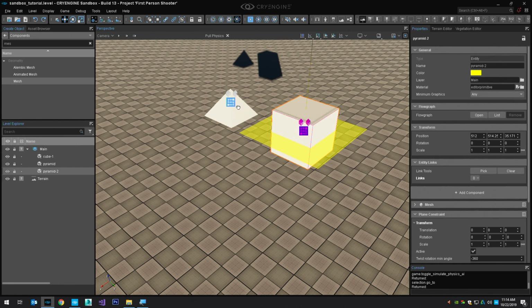So there is damping on entities. That constrains the movement of the entity in the world. Small values are going to be your friend, like 0.1 to 0.4. But if you look on the constraint, it has its own damping value. And I do suggest that you put some kind of positive value in there. Again, between 0.1 and 0.4 is a good starting point. Otherwise, for instance, on the bell, it would just swing and swing and swing, which isn't very real.